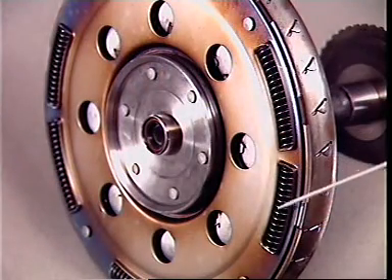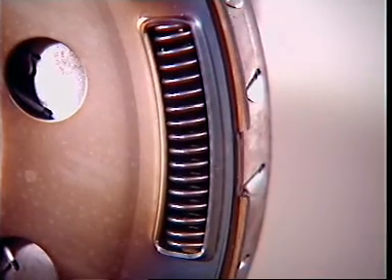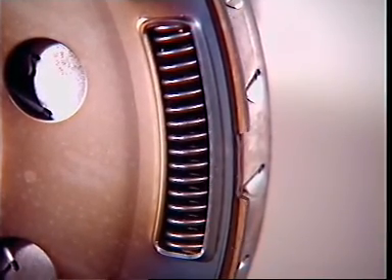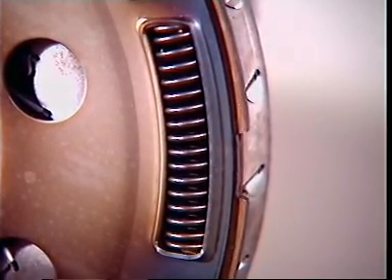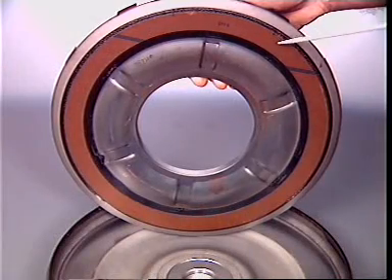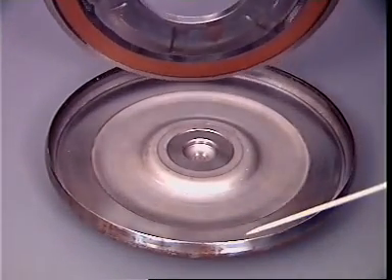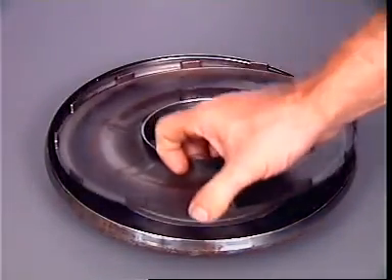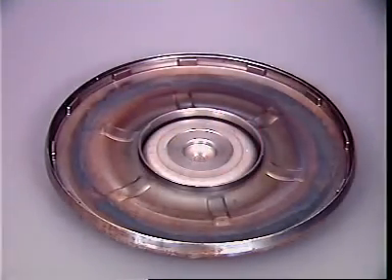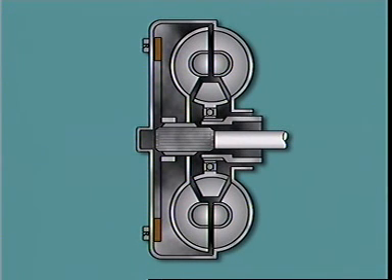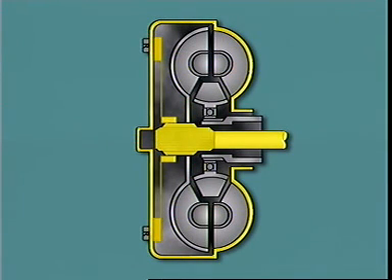Torsional damper springs are built into the turbine piston assembly. When the clutch is engaged, these springs dampen driveline and torsional vibrations. When the clutch facing on the piston comes in contact with the internal machined surface on the wall of the converter housing, lockup occurs. This provides a one-to-one connection from engine to transmission with no slippage between components.